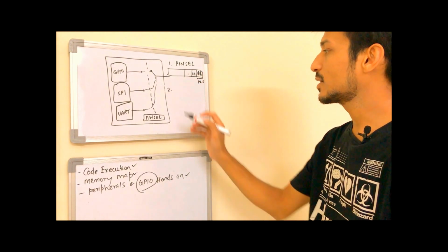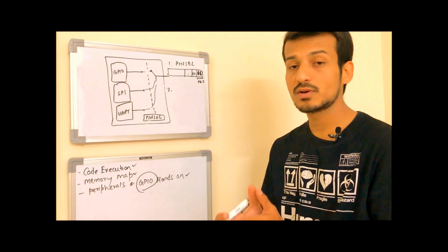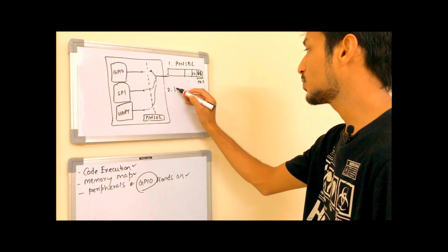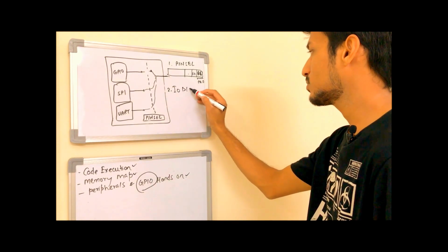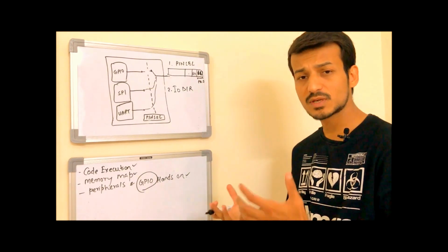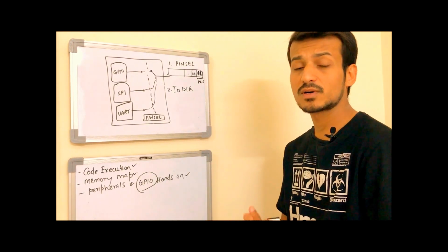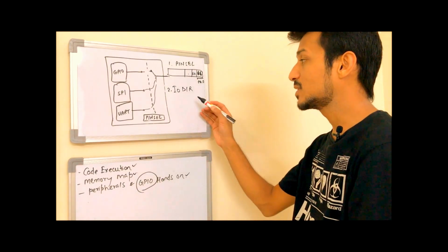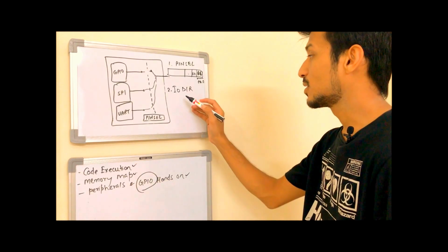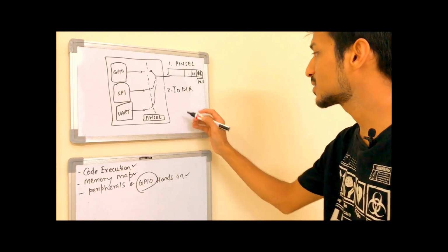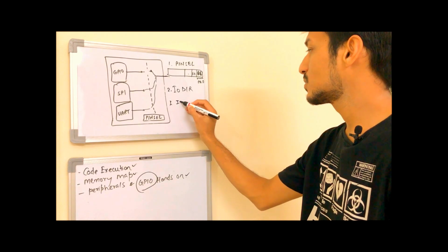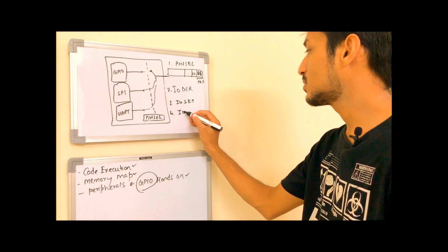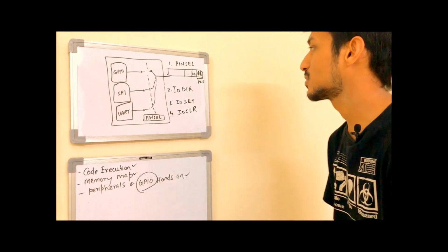Second thing is you have to change the direction. You have to make it an input or output. For that you will use the IO DIR register. I was telling about the DIR register: in the Atmel microcontroller you will have the data direction register, which is DDR. In the LPC controllers, which I am going to use today, the LPC2138 has the IO DIR register. Then the third thing is the IO set register, and another register is the IO clear register.